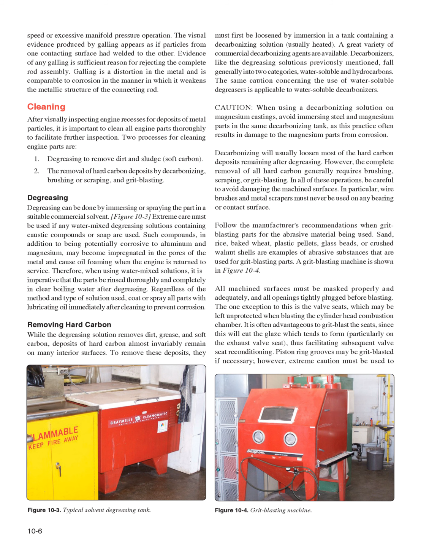Extreme care must be used if any water-mixed degreasing solutions containing caustic compounds or soap are used. Such compounds, in addition to being potentially corrosive to aluminum and magnesium, may become impregnated in the pores of the metal and cause oil foaming when the engine is returned to service. Therefore, when using water-mixed solutions, it is imperative that the parts be rinsed thoroughly and completely in clear boiling water after degreasing. Regardless of the method and type of solution used, coat or spray all parts with lubricating oil immediately after cleaning to prevent corrosion.